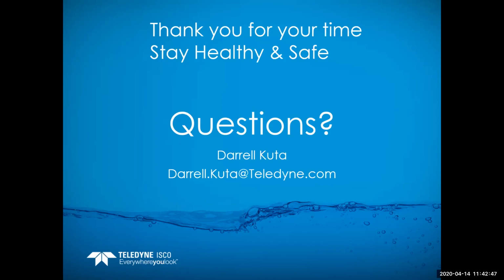Another question came in: is it critical to install a stilling well off of a flume to measure the flow? No, stilling wells are not required. They do make it easier, as far as installing a level sensor and taking a level reading, because the stilling well by design creates a nice smooth surface to give you the average level, but it is not required. And in fact, I see a lot of applications that don't have the stilling well.